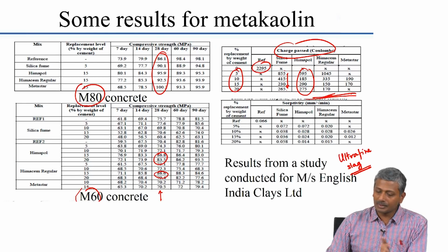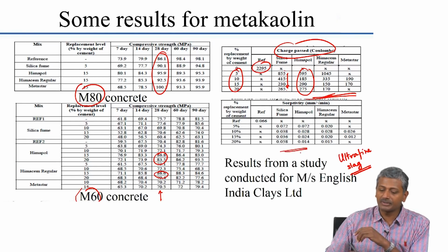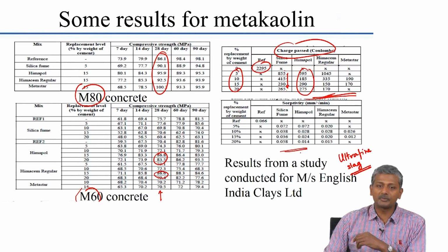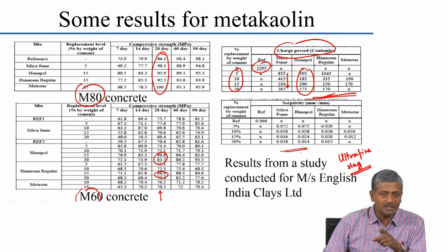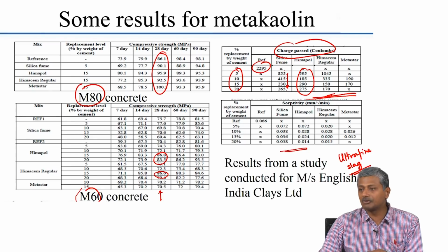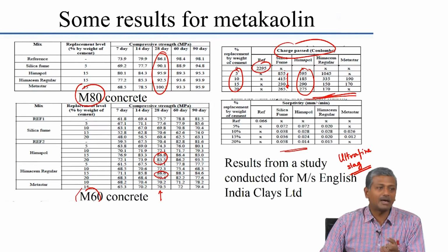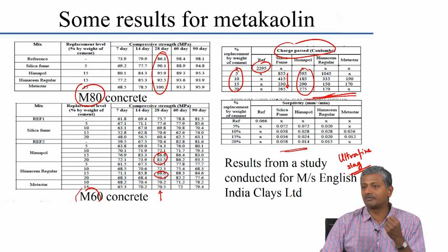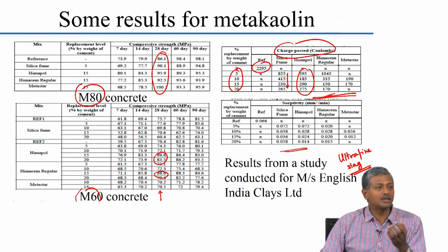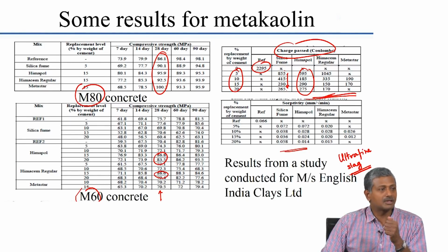But in terms of other durability characteristics, for example, the sorptivity or water absorption potential, you may get similar performance characteristics. But with RCPT, ultrafine slag does not give you the same result as silica fume or metakaolin. Again, this is mainly because silica fume and metakaolin, the finely divided grains, can actually capture the alkalis quite effectively and lower the conductivity of your system tremendously. Slag can do that to some extent, but not as much as silica fume or metakaolin.